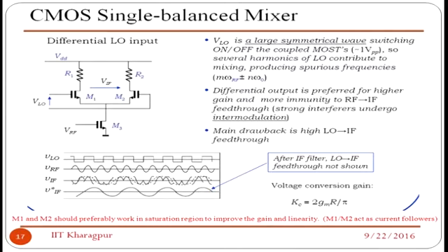So you need to concentrate on this profile that I have cartooned here, showing how physically the frequency translation occurred. Two frequencies, one is the LO and the other one is the RF. They are nearby because the LO frequency and RF frequency are close to each other, except for the modulation. But while they are multiplying or switching in a differential stage, you will find the IF profile in that way.